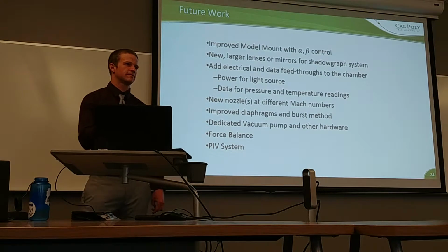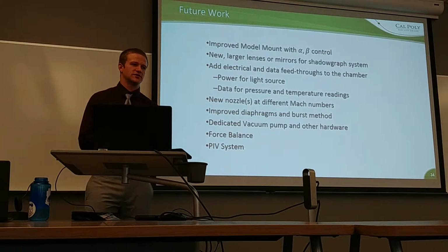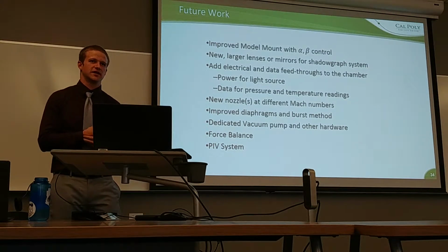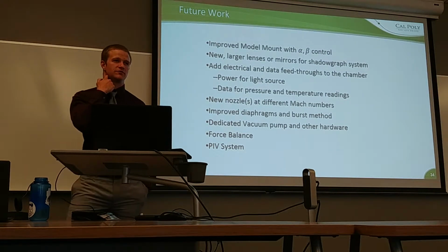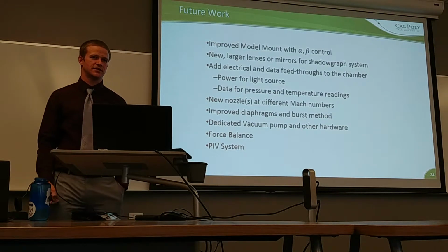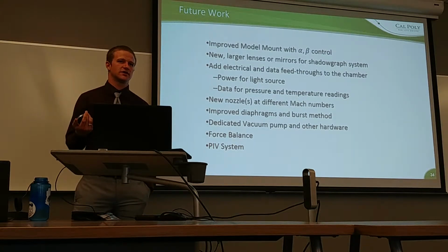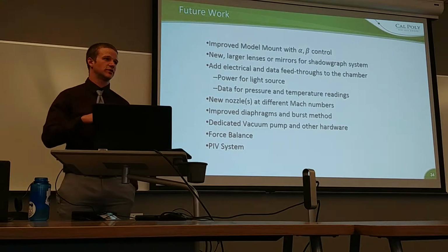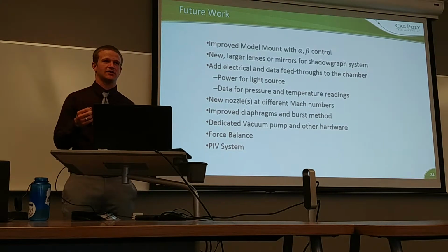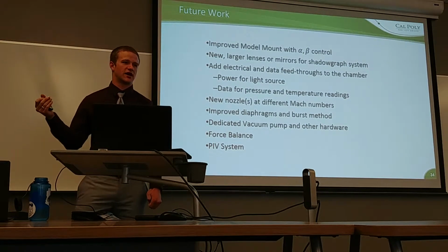I truncated some of the details, because going over every single minute detail of the project would have taken hours. But one of the problems that we had for testing was that the diaphragms would slip out from between the inlet bell and the inlet adapter where they were clamped. It was found that one of the pieces, the machinist who made it, didn't machine a smooth, flat surface into one of them, so it would grip the diaphragm really tightly on one side and loosely on the other. So as we got to low pressures, the diaphragm would slip out.